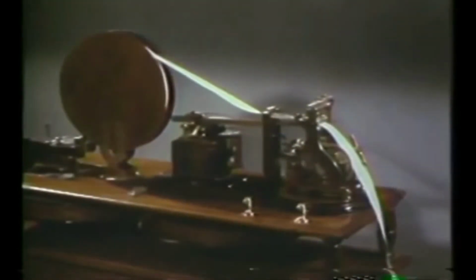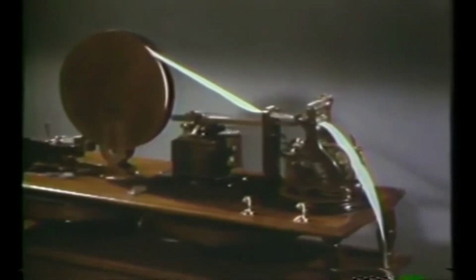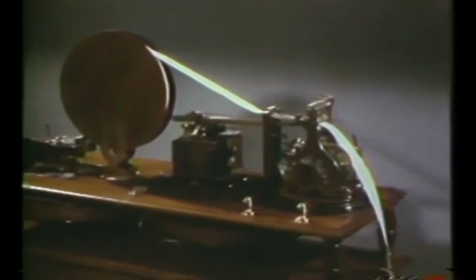By 1846, the perfection of the Morse telegraph register, first conceived in 1837, made possible a comparison of the time difference, and hence the difference in longitude, between two chronometers at two widely separated stations by means of signals transmitted over a telegraph wire between the two stations. The respective local times at the two stations were determined by observation of the meridian transit times of selected stars and comparison with a portable chronometer according to a procedure known as the eye and ear method.